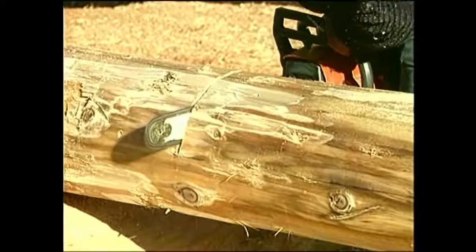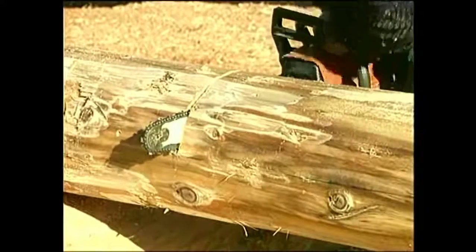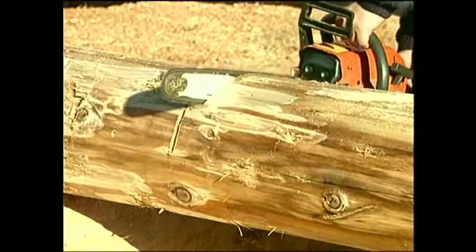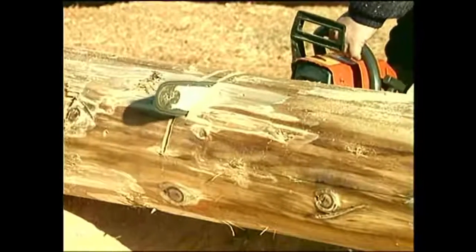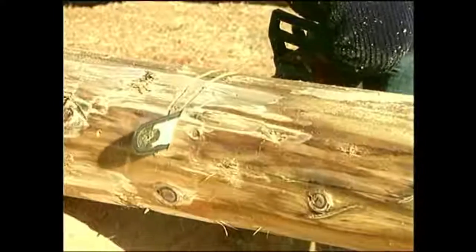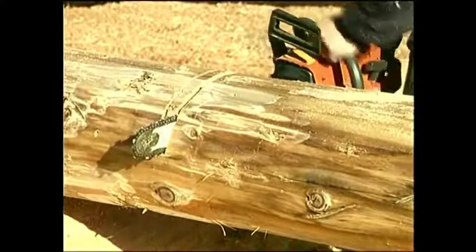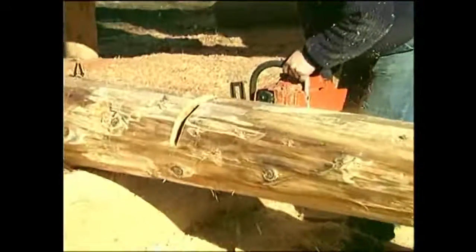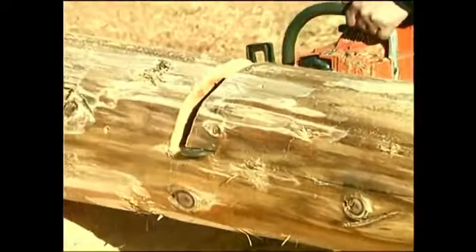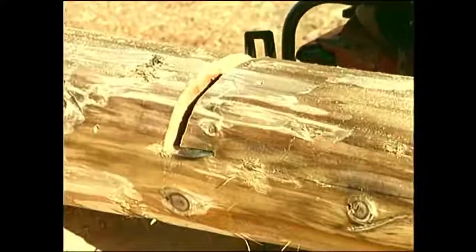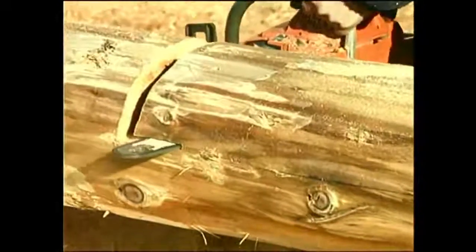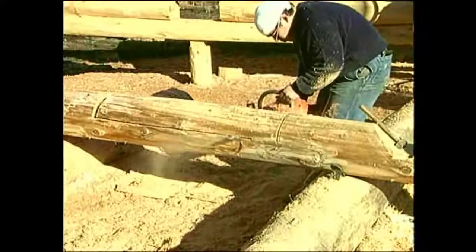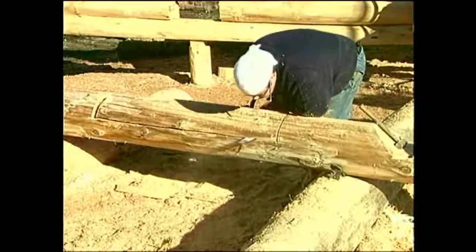Continue the cut to within 5 millimeters of the line and make sure that it's straight on the bottom. Now make a second cut right alongside this one and clean it out to the line. This will allow you to watch the tip of the saw as you plunge cut through. Then continue this cut to the end, and as usual, be cautious that you don't overcut any of the lines.